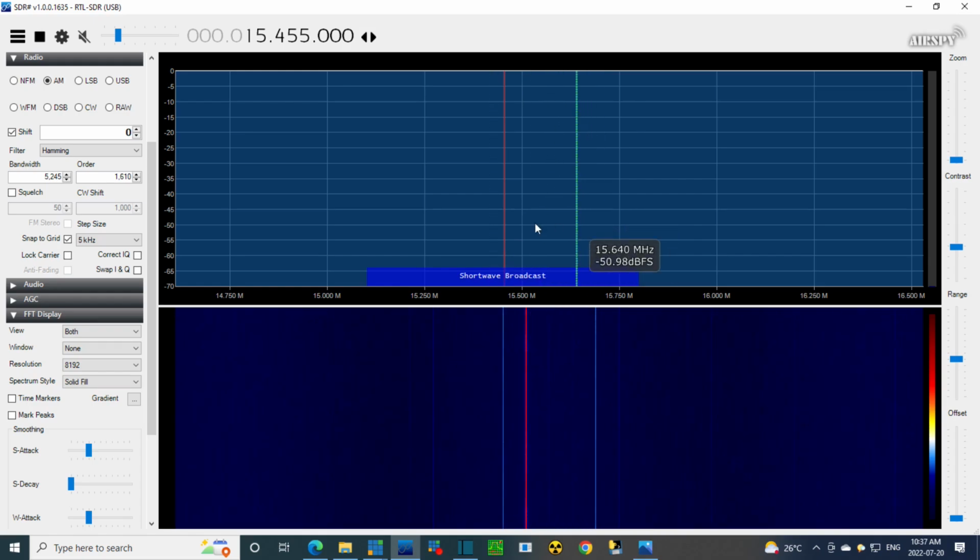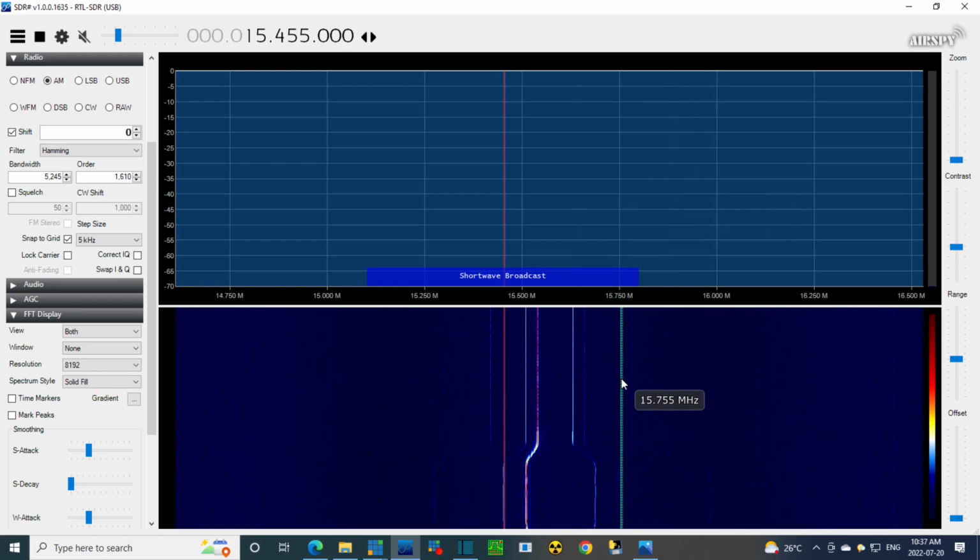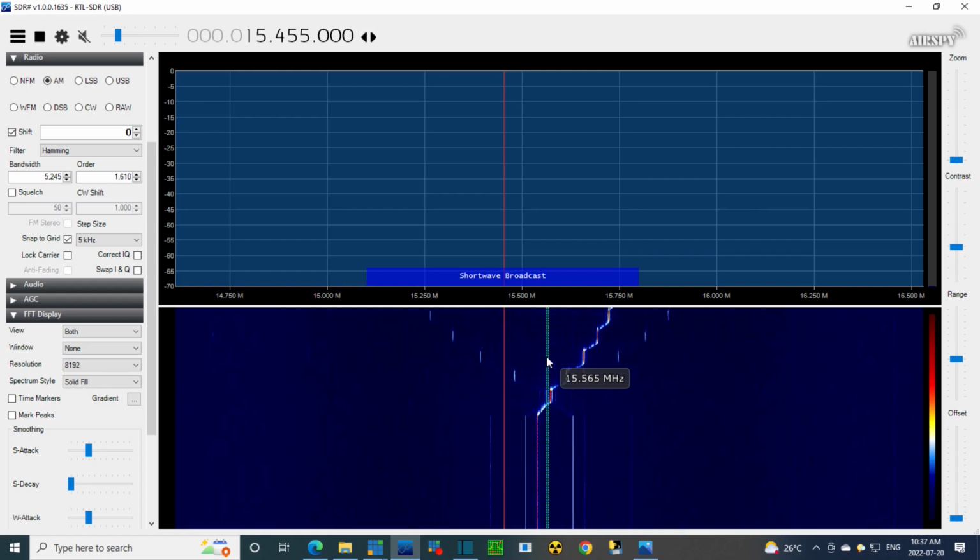So again, alignment is out. But the local oscillator is there. It's right there. And it's red, which means it's a fair strength. What do we find out? We found out the oscillator is oscillating. Let me go to the top of this band. This is the stress test on the radio. Actually, this isn't the stress test. Still there. Yep. Still there just fine.